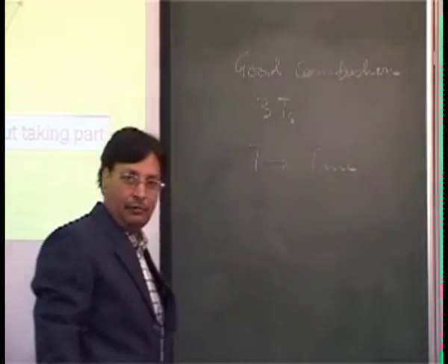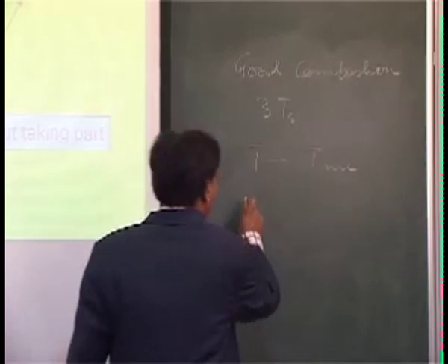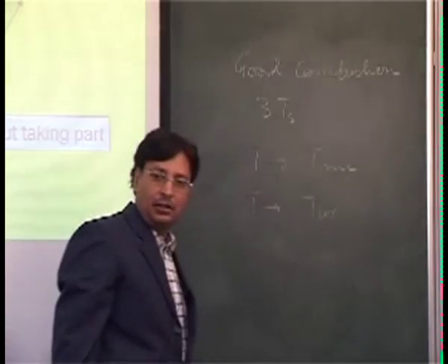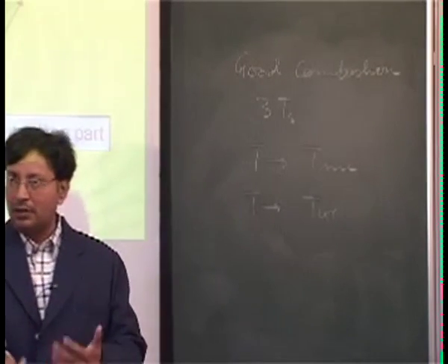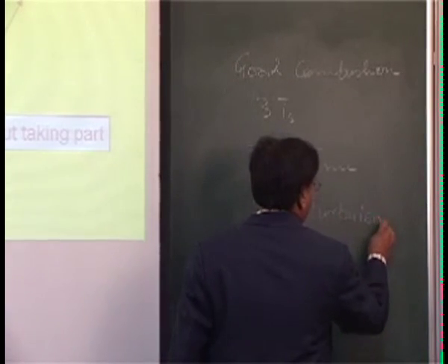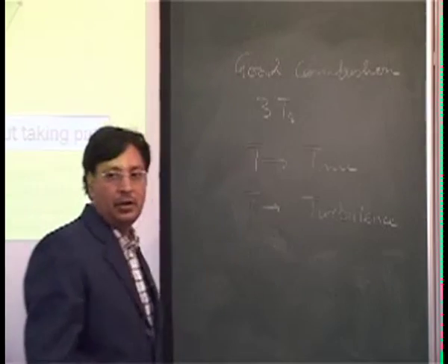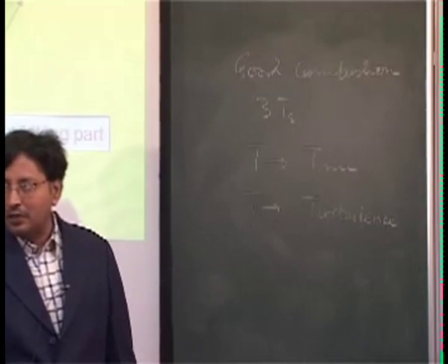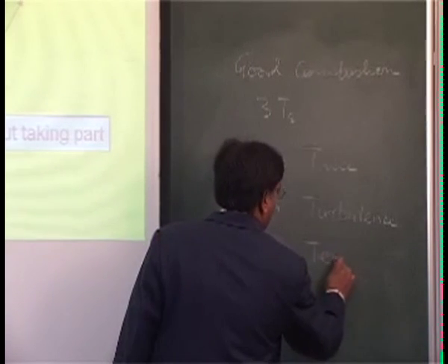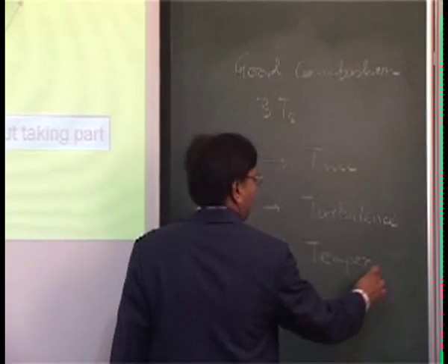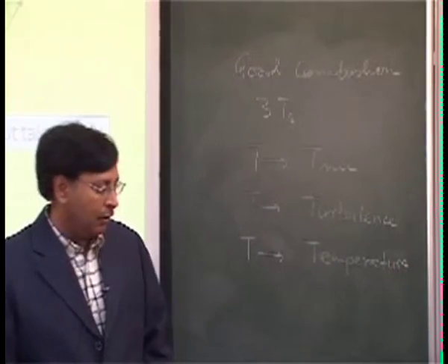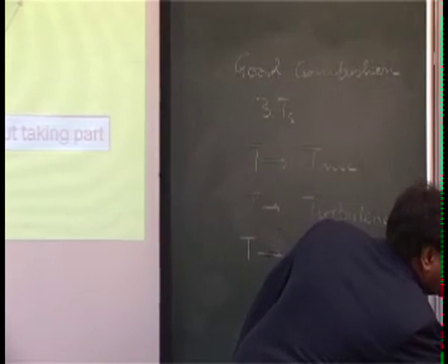You have to give enough time for the reaction to happen. You have to have the right amount of turbulence. Combustion is a surface phenomenon, so you need turbulence. If there is no turbulence, you can't have proper combustion. And third, and very important, is the temperature.